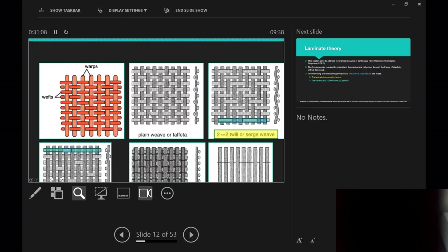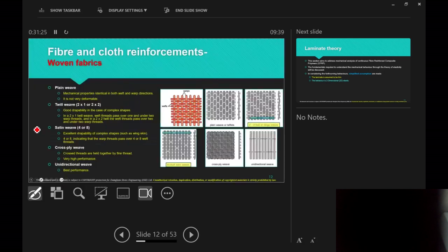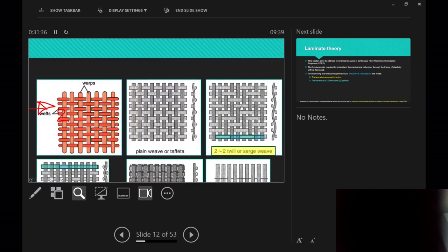So that was weft, right? So weft goes above one, under another one, above, under, above, under, above, under, as you can see. They call it plain weave. Because of this setup, the modulus of elasticity you get in that direction is called direction 2. That's direction 2, that's direction 1. So the modulus of elasticity E2 is essentially the same as E1.